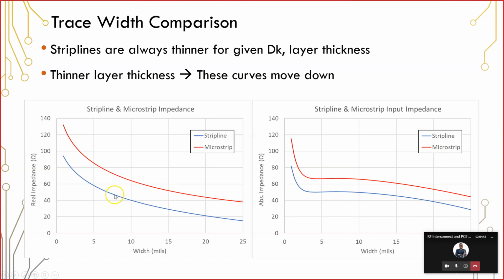And so the result here that you can see is that the strip line and microstrip can have very different widths for the same impedance. Here you've got almost a factor of 3 larger microstrip compared to the strip line. So if you're routing with microstrips, just note that if your calculator tells you you need to have a very wide microstrip, then it's probably not incorrect. So just make sure you understand that when you're using calculator applications to design transmission lines.